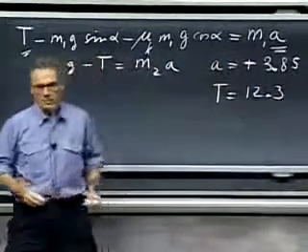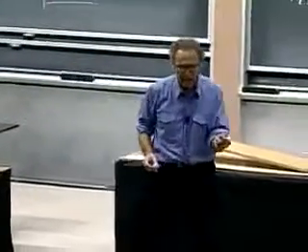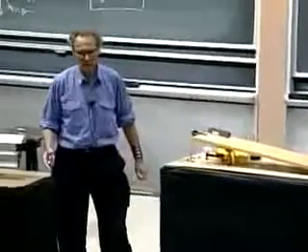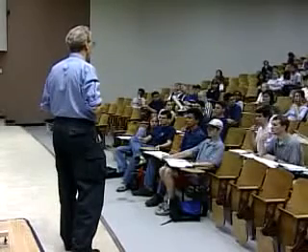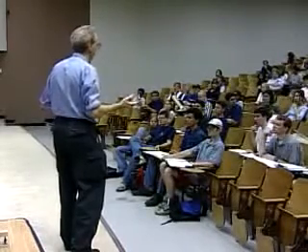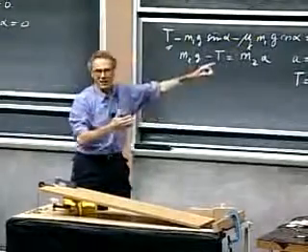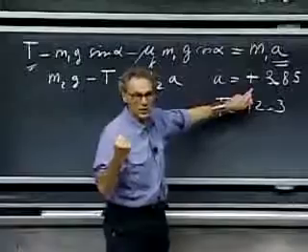I want to dwell on this a little bit. I find for the acceleration a plus sign. Had I found a minus sign, I'm sure I would have made a mistake. Why is it mandatory that I find the plus sign? Absolutely mandatory. Who wants to try that one? Yeah? Well, if you put the friction interaction to opposite acceleration, the accelerating direction friction. Yeah, you say it well. I would have said it slightly differently. We know that the acceleration is in this direction. We derive that. Therefore, the acceleration, since I call that the plus x direction, that was my plus sign, must come out plus. So if this comes out negative, you've made a mistake.